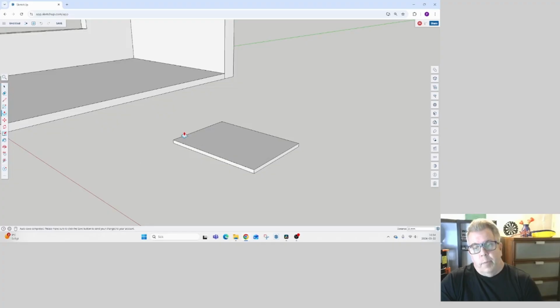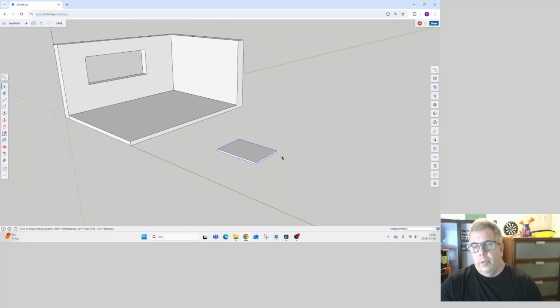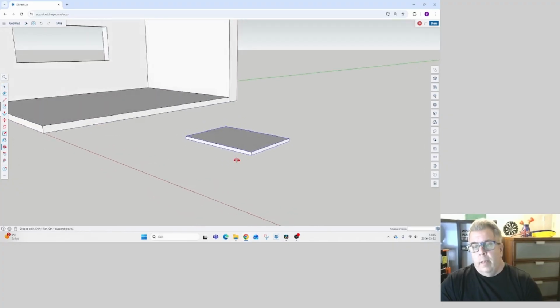And then when I'm happy with that, I can either click the spacebar, or click on select, draw a window around just the table geometry, the tabletop, till it's all selected. Another way you can do this, if I deselect it, is to triple click on the geometry. So 3 times with the left mouse button, everything is selected. Then it's just to right click and make group. So now we've got 2 groups, one group here and one group here.